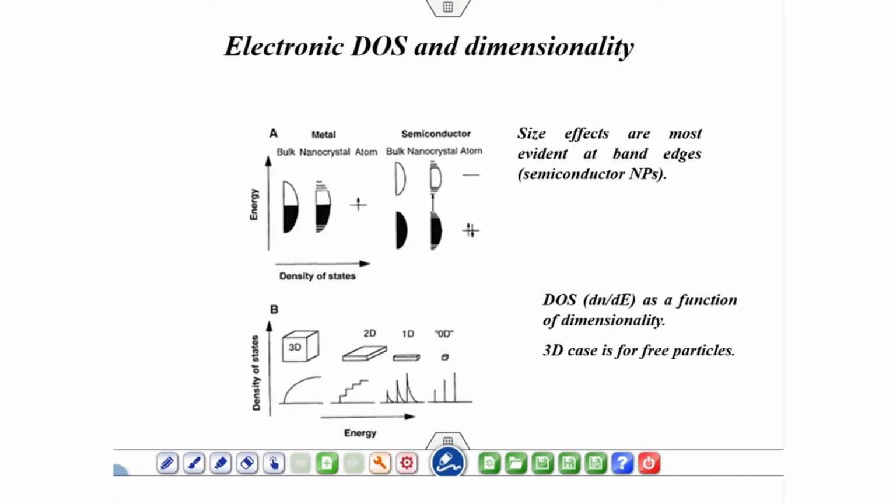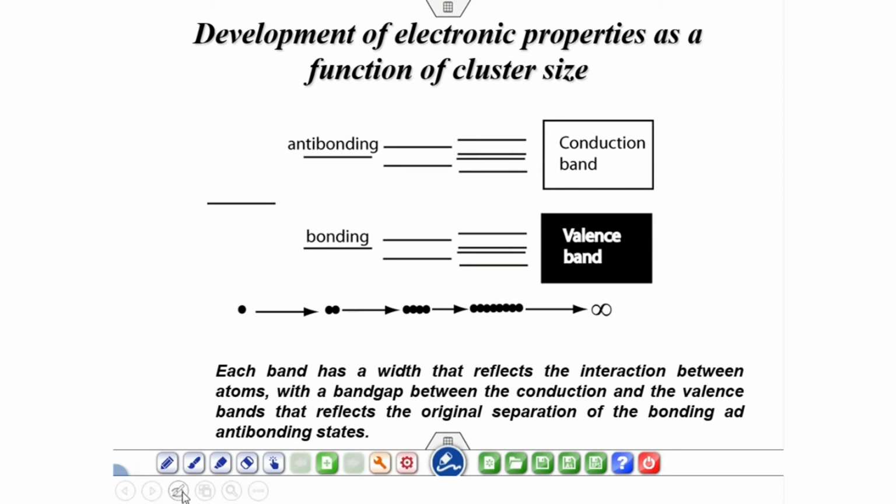So in a metal actually you don't have any band gap, right? There is no band gap in a metal because the valence band and conduction band overlap each other. On the other hand, in semiconductors and insulators, you have a definite band gap. In a semiconductor, the band gap is small compared to the insulators. Therefore, because there is no band gap between the conduction and the valence bands in a metal, what will happen? Because of overlap of these two bands, electrons are free to move. There is no barrier, and because there is no barrier, electrons are delocalized. This is how we have discussed it.